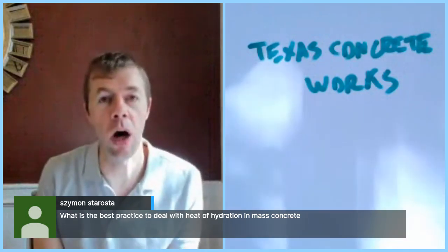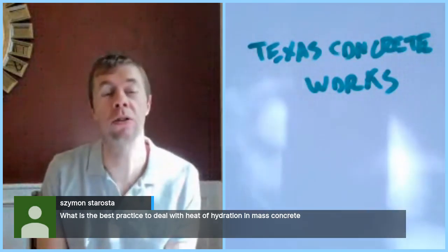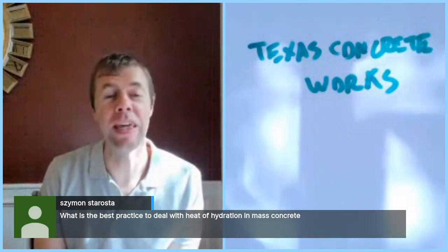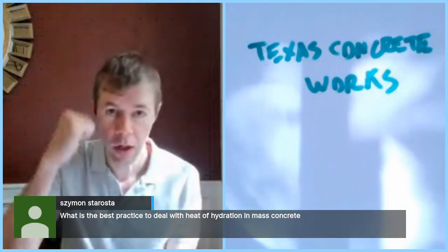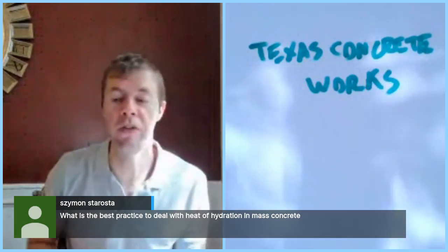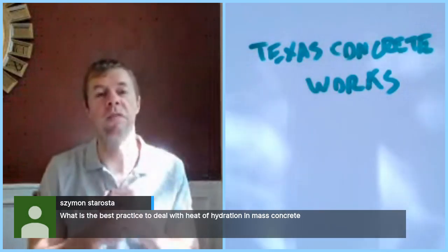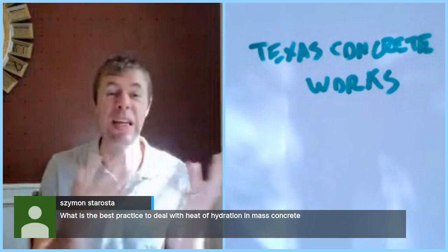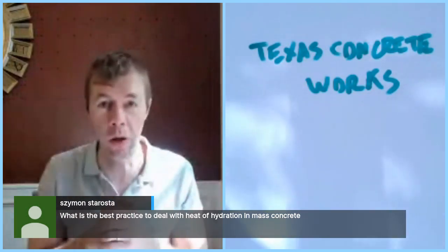Anton Schindler, Auburn University, helped develop it as well, and also John Poole, who is a consultant now kicking tail out in the world. Go JP. But Texas Concrete Works is a very cool software package that helps you evaluate different methods to minimize the amount of heat given off from mass concrete elements.